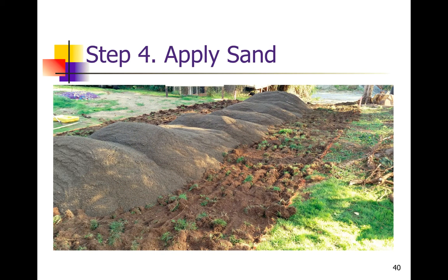Once we've completed the basal prep, we want to apply the sand. This can be done in any number of ways. If you have access and you can back the dump truck right up to the edge of the basal area, go ahead and just dump it out. Others will scoop it out with the excavator from the back of the dump truck. Depending upon the logistics, you may have to shuttle the sand in. Access is the big key here.